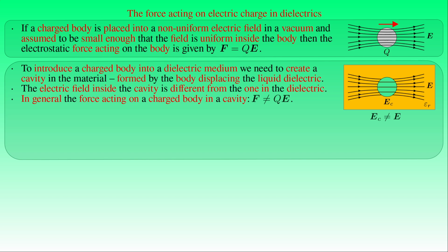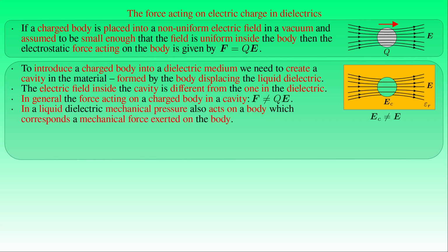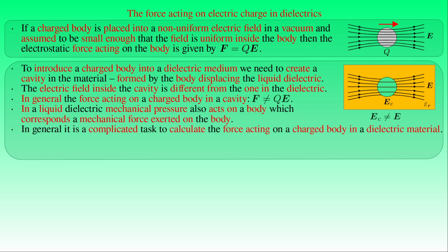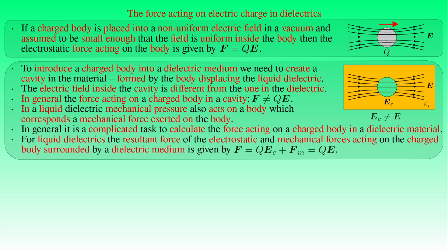If we want to calculate the force acting on a charged body in a liquid dielectric, we must also take into account the fact that a mechanical pressure acts on the dielectric at the boundary of the body, which corresponds to a mechanical force Fm exerted on the body. As a result, the force acting on the charged body in the dielectric cannot be determined by the equation seen above, and its calculation is usually very complicated. In the case of liquid dielectrics, however, these calculations provided a very interesting result, according to which the resultant force F of electrostatic and mechanical forces is equal to the product of the charge Q and the electric field strength E.